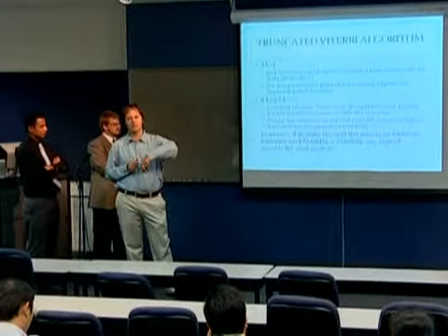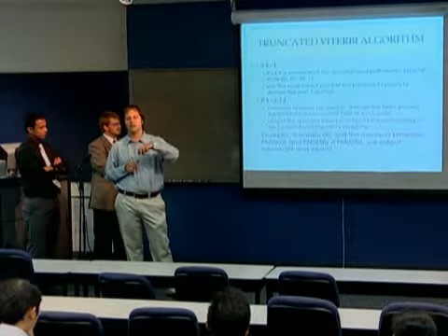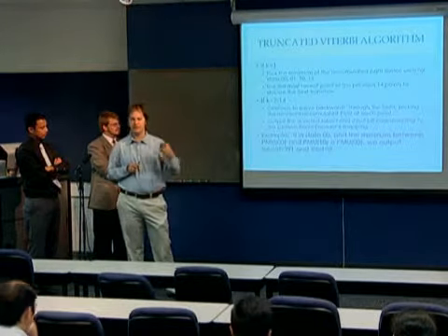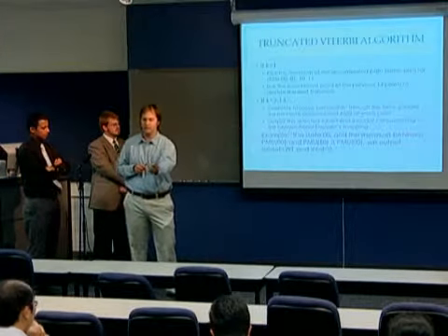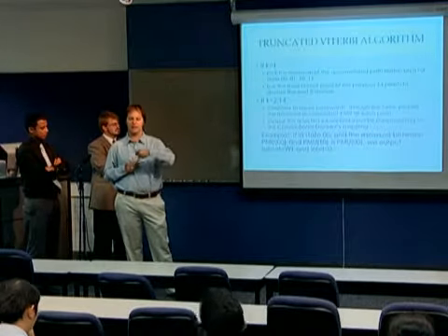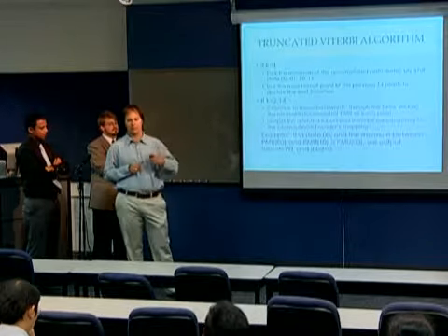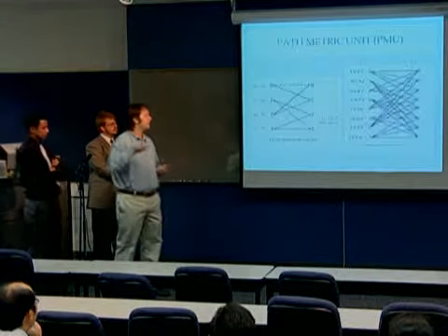So we pick each minimum, and we output the corresponding bit that went into the convolutional encoder to make that transition happen, and we output the subset that was selected for that point.